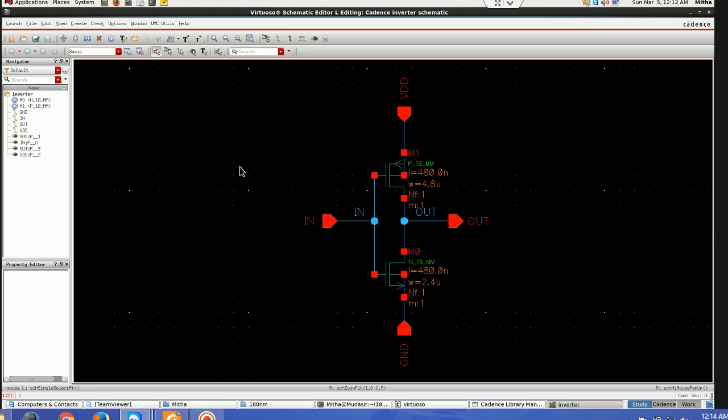These process corners are defined on the basis of the speed of each transistor and interconnect present in our circuit. For example, there are 5 types of process corners defined in Cadence Virtuoso. One is FF, which stands for fast, when both PMOS and NMOS behave as fast transistors. Similarly, there is SS, where both behave as slow, and there is fast PMOS slow NMOS, and fast NMOS slow PMOS. And one is typical. Most of the simulations I have done so far, I did considering the typical condition.